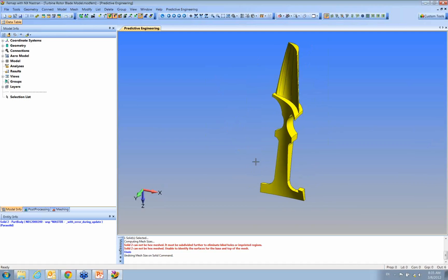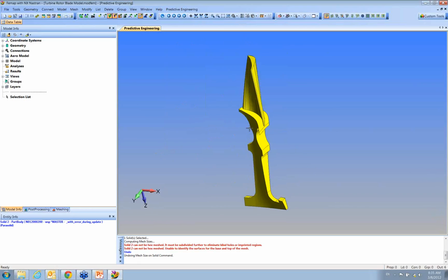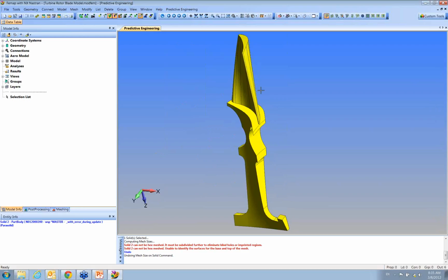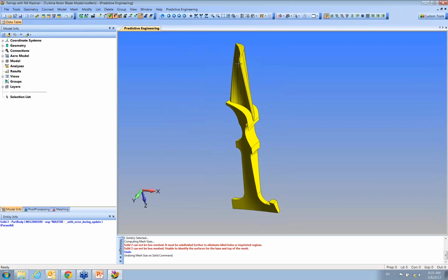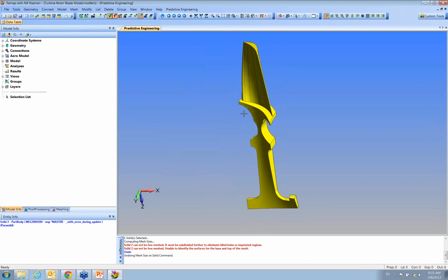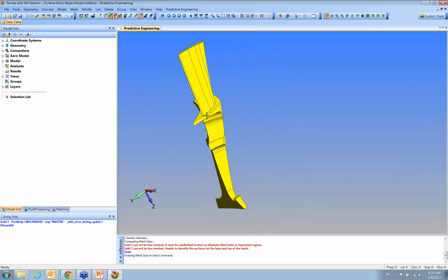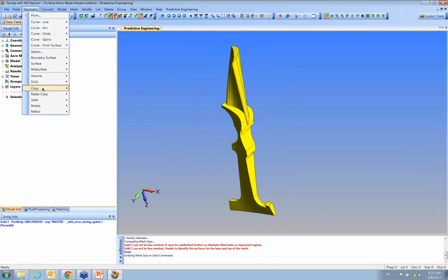And let's look at how we would hex this. And people that have been working for a while with hexing would say, well, it would most likely hex if we get rid of this blade on top and hex this part and then conquer this separately. So slicing something like this, well, yeah, it's not flat, it's not curved, it can be tricky. Here is what was shown to me.